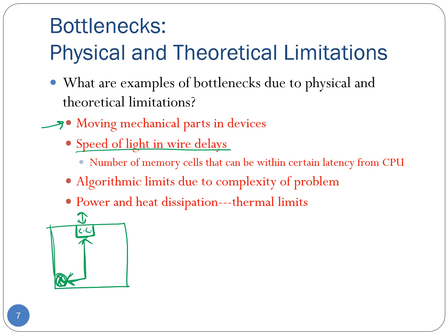Even if everything else takes zero time, the wire delay, the time it takes for the signal to traverse this wire, is dictated by the speed of light. So essentially, as you could imagine from here, the size of your cache in some sense determines the speed with which you can access data stored in the cache. So this is an example of how the speed of light and wire delays affect or become a bottleneck in our computer systems.